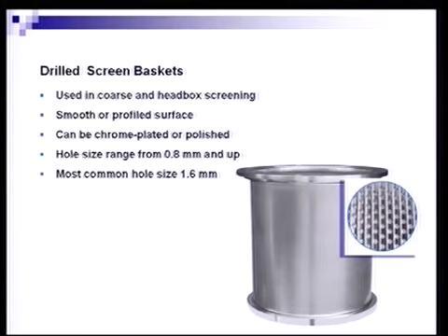This is the heart and soul of any pressure screen, would be the screen basket. This screen basket is the partner to the rotor, and between these two components is what really performs the duty of the screen, which is to remove the debris that is large in two dimensions. That is the flake content that comes to the screen from the pulp that is removed from the pulper, specifically in a continuous pulping loop, will have a fairly high flake content, for instance, for packaging grades. And coarse screens are required to be operated ahead of slotted screens or fine screens because the coarse screens will remove the flakes much more effectively.